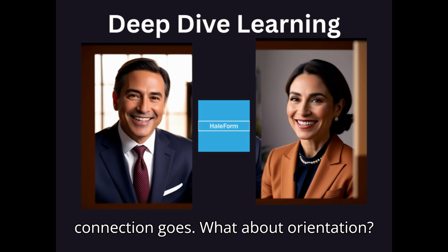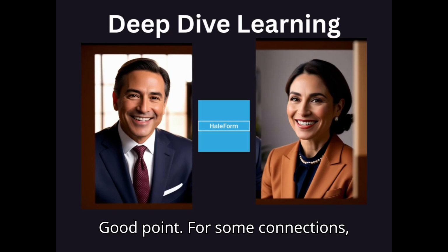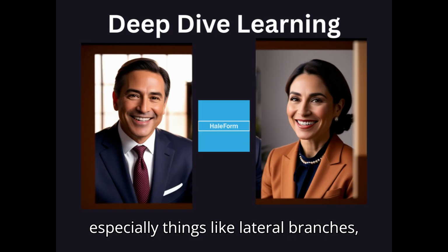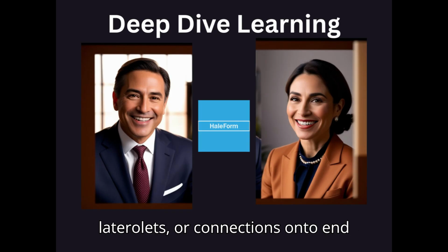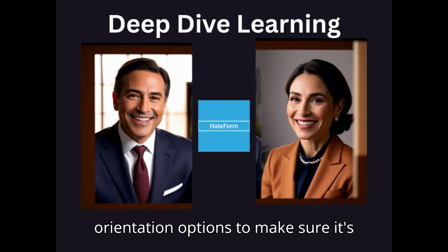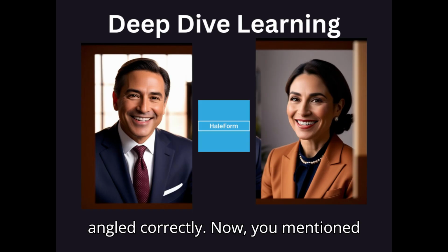What about orientation? Good point. For some connections, especially things like lateral branches, lateral lets, or connections onto end features, you'll use the component orientation options to make sure it's angled correctly.